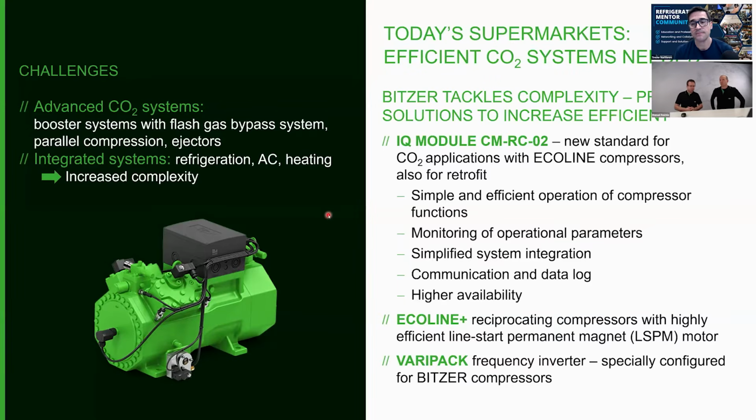Because it was a field test case, we went back to the service guy and asked, hey, can you look at the maintenance log? Did you put additional oil into the system? Yeah, and then they found out different service technicians had refilled oil 3 times. So it was massively overfilled with oil, causing the next challenge for the compressor, because it's running as an oil pump. It's not good for the long term.